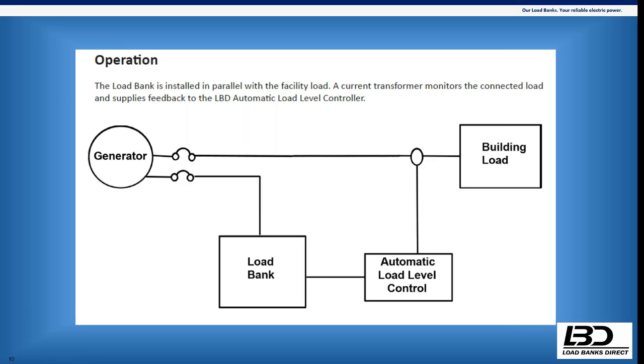Yeah, so it is a fairly simple concept, and it's definitely one of, if not the most common options that we sell on our permanently installed load banks, because it's a huge pro. It reduces maintenance requirements on your generator, not having it sitting there idling all the time, and increases the lifespan of the generator.